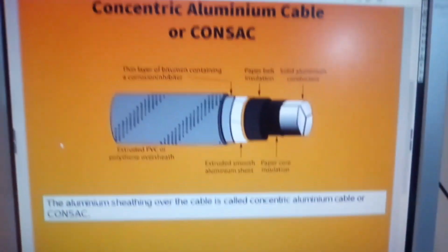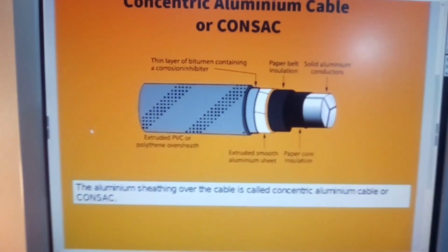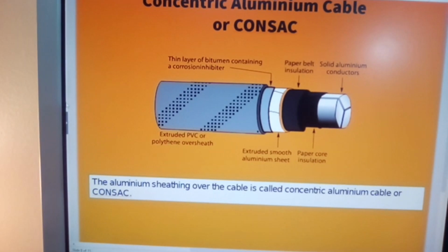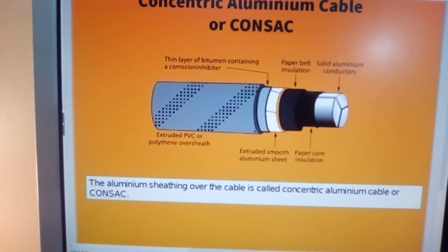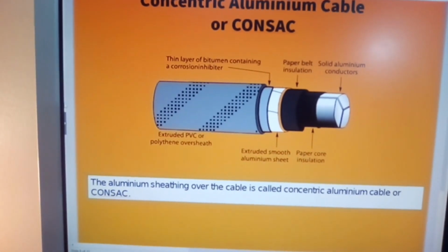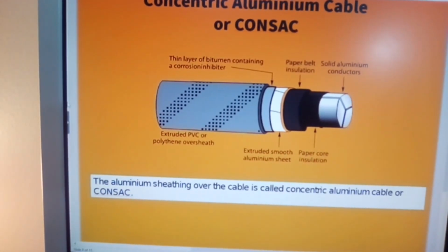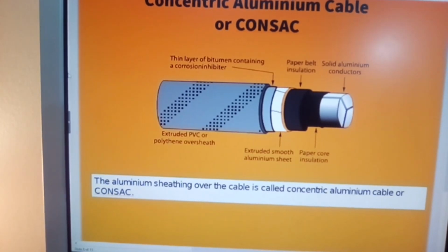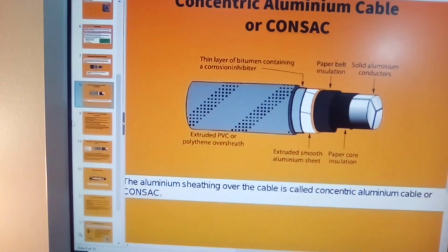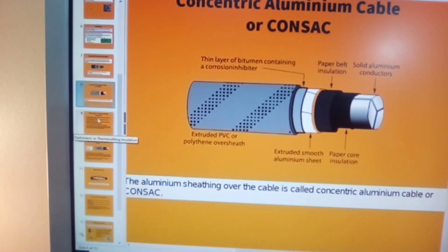Solid core because with regards to aluminium, aluminium would break. You have to be careful with that kind of connection, and you can only get aluminium cables to a given size before it becomes basically unusable because of the potential to break at termination.